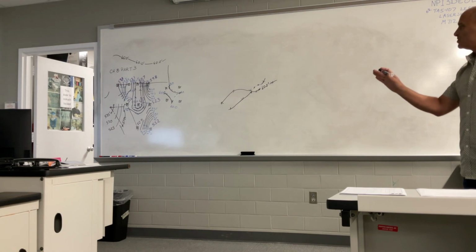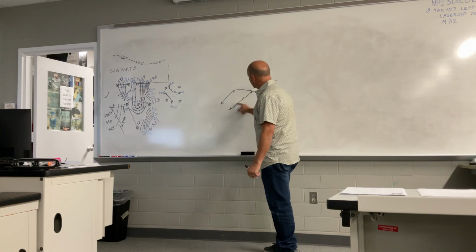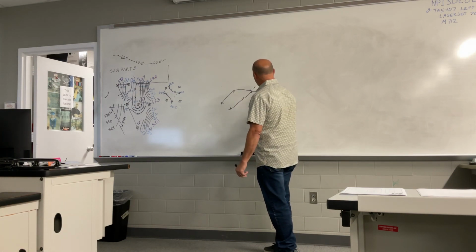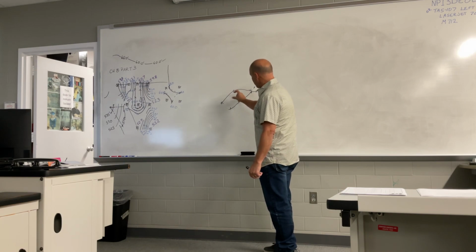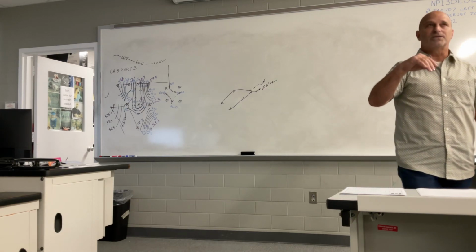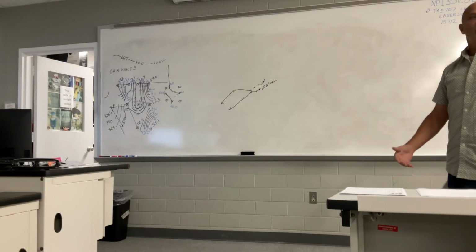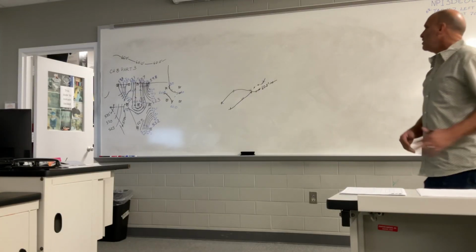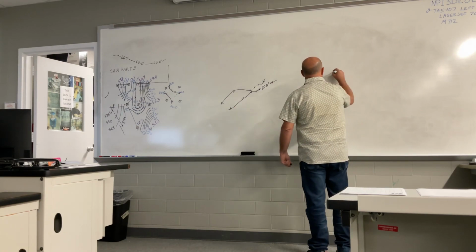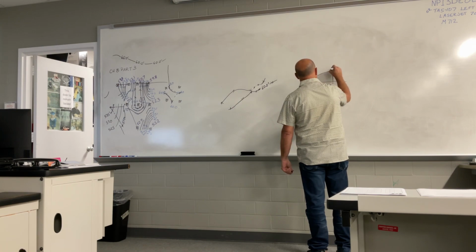And that way, as you position it, as you take that one right here and you copy it over here, you don't have to go back and trim or break that spline. You could take it over here and maybe rotate it, because we want our text to be in the same position as our contour behind it. Remember your text rules in here. We don't do anything text dimension wise or text label direction wise. We don't do anything over 90 degrees all the way around to 270 degrees.